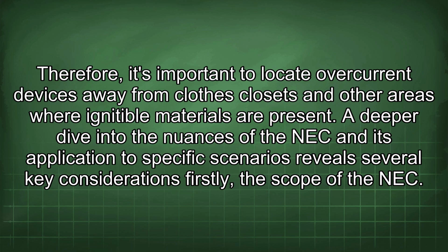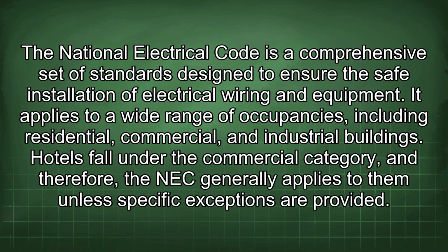A deeper dive into the nuances of the NEC and its application to specific scenarios reveals several key considerations. Firstly, the scope of the NEC. The National Electrical Code is a comprehensive set of standards designed to ensure the safe installation of electrical wiring and equipment. It applies to a wide range of occupancies, including residential, commercial, and industrial buildings. Hotels fall under the commercial category, and therefore, the NEC generally applies to them unless specific exceptions are provided.